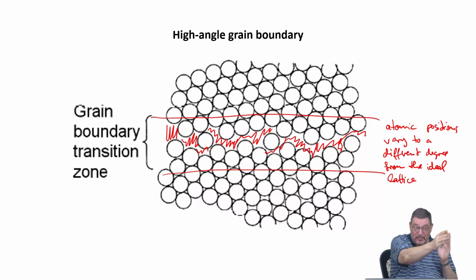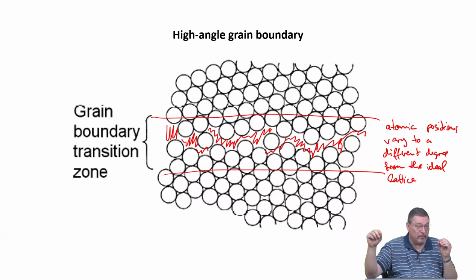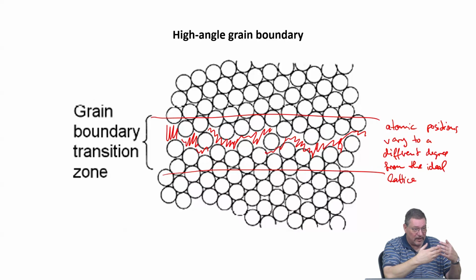What does a dislocation do? You're absolutely right. Grain boundaries are sinks for dislocations, so they move into the boundary. What happens to the dislocation once it's in the boundary, in a high angle grain boundary? It dissociates, it loses its character. It can become a secondary grain boundary dislocation, but then the Burgers vector of that secondary grain boundary dislocation is different from the original Burgers vector, which is defined by the crystal lattice it was coming from. So it means dislocations, once they went into the gap, into the sink, are no longer the same dislocation. They split up, they dissociate, they become something different.